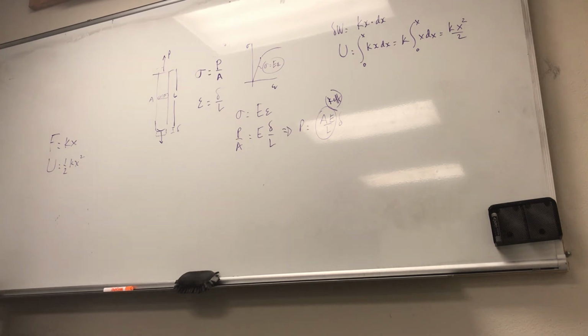If you have a cantilever beam that has the length L, and you put the end load on it, what the cantilever beam tells you is that it's going to deflect an amount delta equals to this. That kind of makes sense because the higher the load, the more deflection. The longer the length of the beam, the more the deflection, right? The lesser the area moment of inertia, the more, etc.